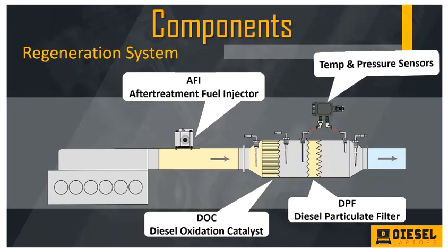We have temperature and pressure sensors. If we have an exhaust stream that's getting up to 1,000, 1100, 1200 degrees, we should probably monitor that for safety, right? But it's not just for safety, it's for diagnostics, it's for ECM diagnostic tests, it's for us as technicians to figure out the problem. So it's really nice to have these there.